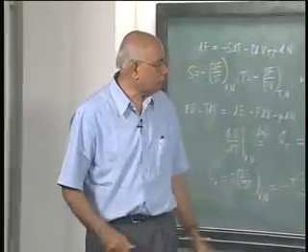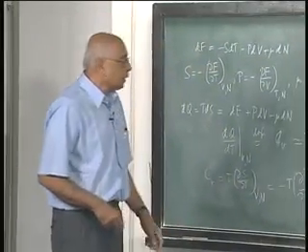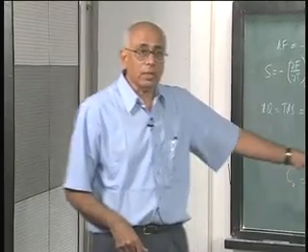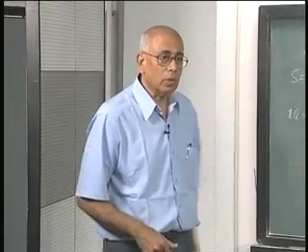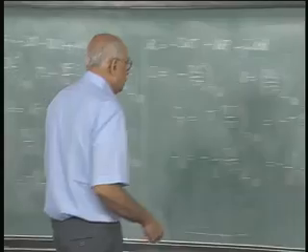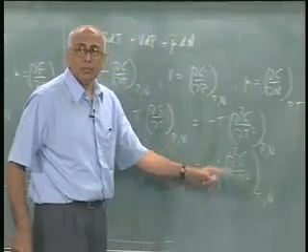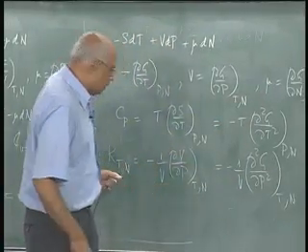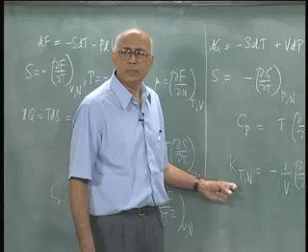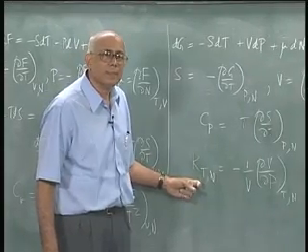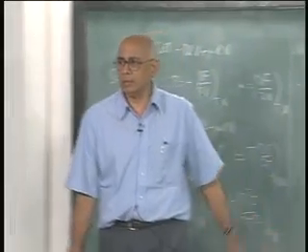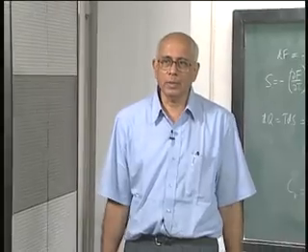So that's the order of magnitude of this quantity. Now the isothermal compressibility must always be positive. Incidentally, how is this related to the bulk modulus? It's the inverse of the bulk modulus, the reciprocal of the bulk modulus, right.